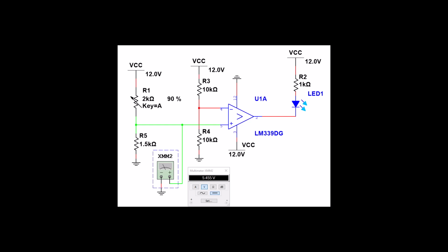Here's another circuit that we just talked about. This is our nightlight sensor. This is a phototransistor, and when it has a little bit of light, it's a high resistance. Right now it's dark and the light is on. Once it gets lighter, we should eventually turn that light off. So let's try it out.